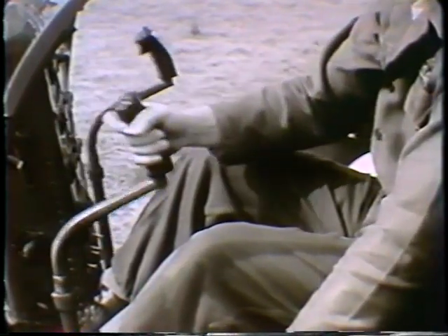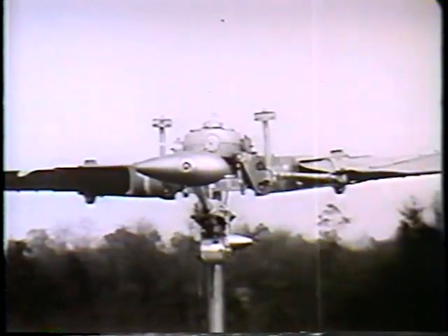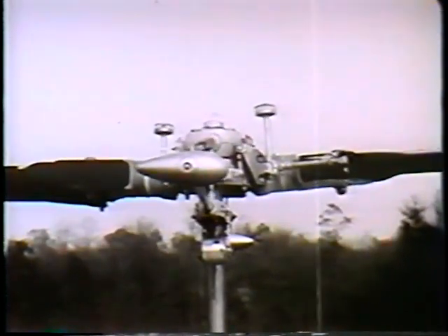By applying cyclic control, lift is increased on one half of the rotor disc, decreased on the other half, and the disc itself is tilted. The helicopter will fly in whatever direction it is tilted. This, of course, results in a change of attitude of the aircraft. The helicopter is capable of many maneuvers once deemed impossible in an aircraft. Knowledge of your rotor blade angles is a solid foundation on which to build a full understanding of the principles of helicopter flight.